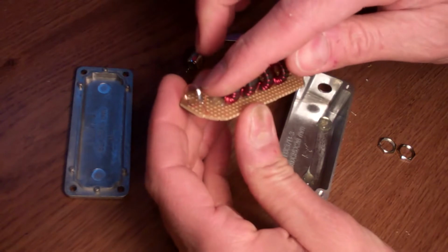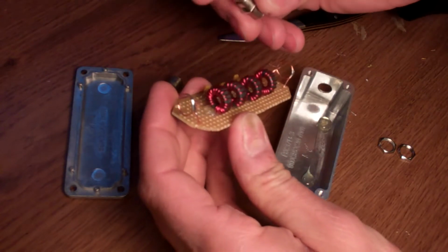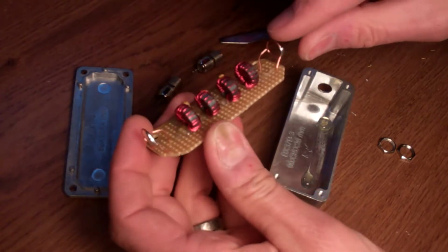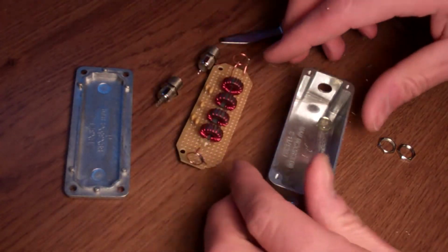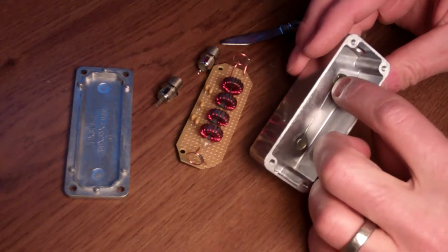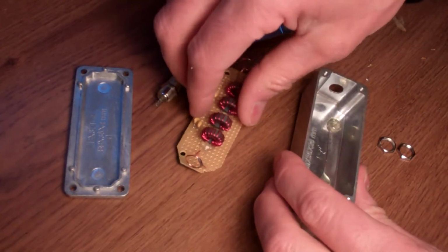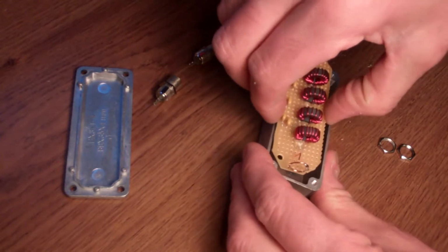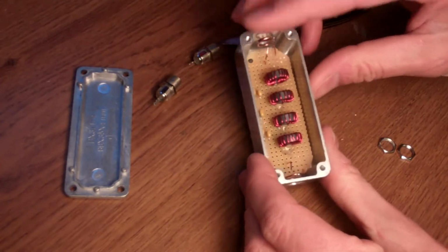I've taken the leads and put them in position for where the connectors will be soldered and/or set through these. Put a little solder on this to hold them into place. And in the box I put two little pedestals of hot glue, which will help support this, keep it even and aligned up for the F connectors, which will fit in just like this.